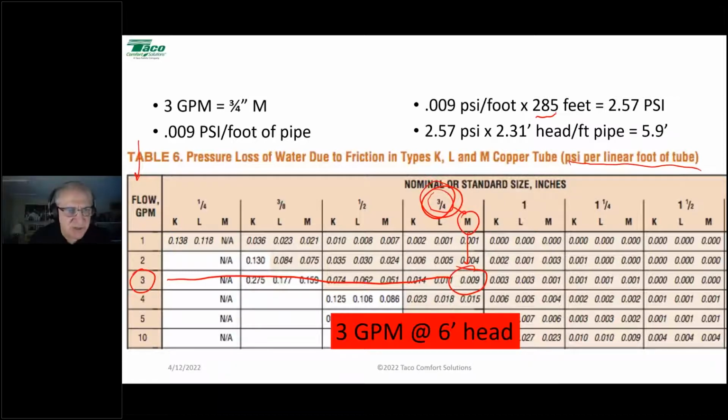Bill O'Donnell asked a question: are there velocity limits in copper piping in heating? Please discuss. Absolutely. That chart that is included in your handouts has velocity guidelines. Typically speaking, we're looking at a velocity maximum of 4 feet per second in our piping. We want a minimum of 2. We want to stay under 4 feet per second.